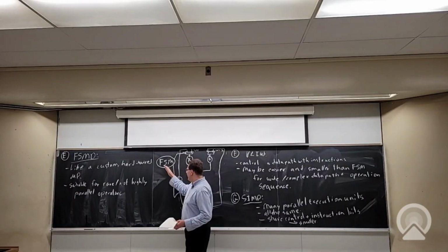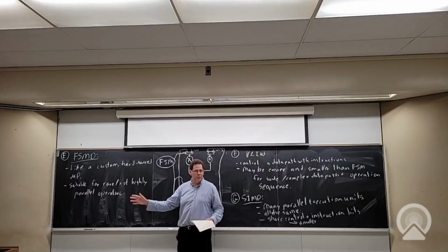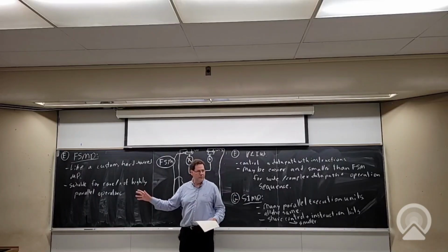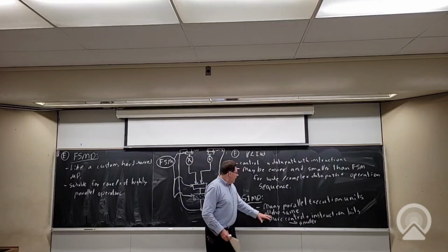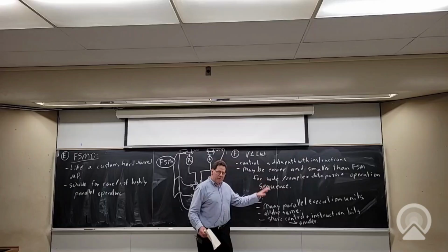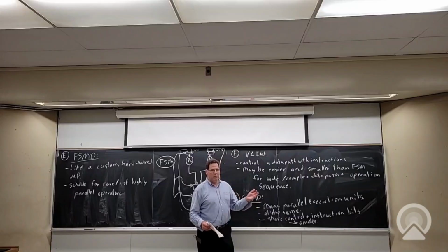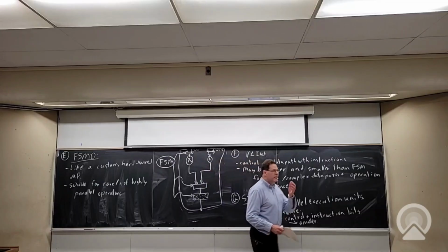Instead of having a finite state machine that produces 500 control signals, maybe a finite state machine that produces a smaller number of control signals, they get kind of broadcast to a bunch of function units. So by saying my control will do the same thing to a whole bunch of data elements every time, it factors out your control, right? I need like one copy of my control logic instead of having effectively 50 pieces of control logic to control 50 functional units.